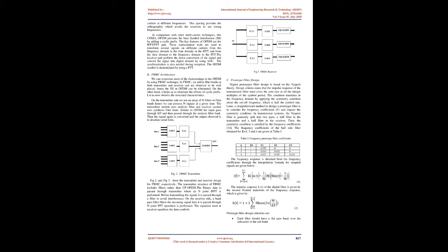In this paper we analyze a performance comparison between the OFDM method and FBMC. The OFDM symbol has a high peak to average power ratio, PAPR. This high PAPR causes nonlinearity effects on the transmitted OFDM symbols, spectrum spreading, intermodulation, changing signal constellation, and interference to symbols. It is more sensitive to carrier frequency offset and interferences. Meanwhile, the FBMC technique offers low PAPR and better performance parameters compared to other schemes.